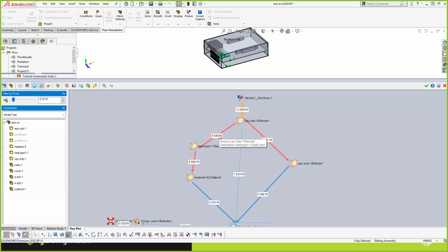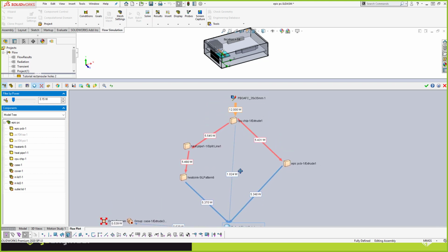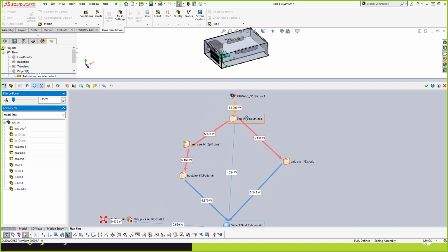You can see that a lot of it went to the, I guess if we decrease the thermal resistance of that grease that we used, maybe we can get more heat going this way and lower this temperature in the top here. This is kind of a nice graphic. You don't get this out of the SimPro thermal analysis. It shows you those heat pathways. You sort of have to manually probe your model to try to get something like this out of there.